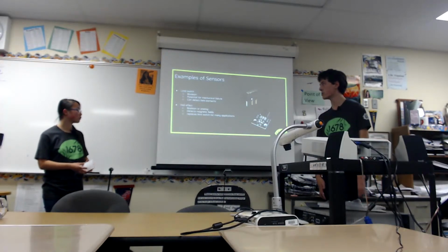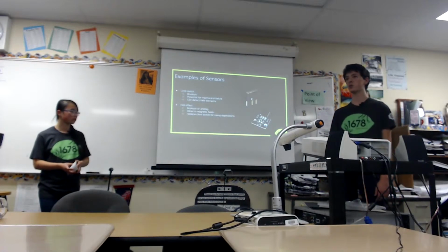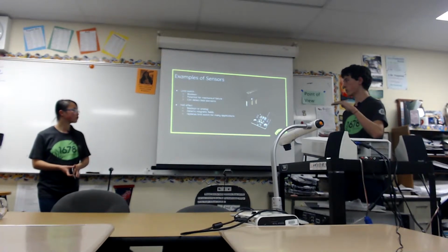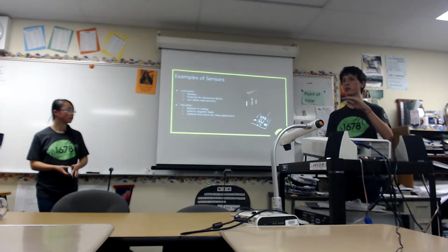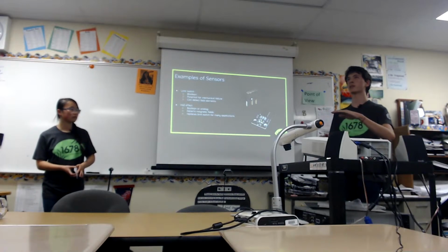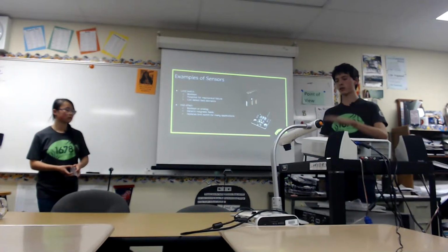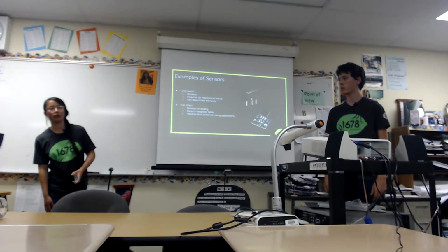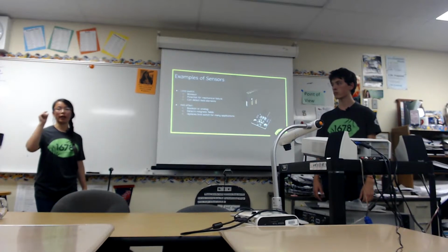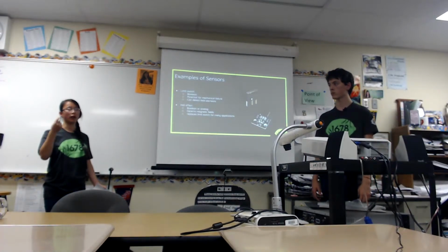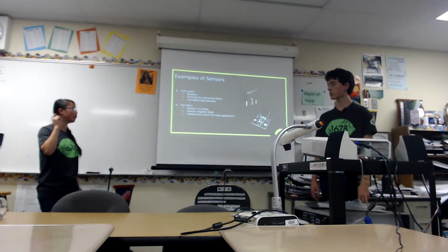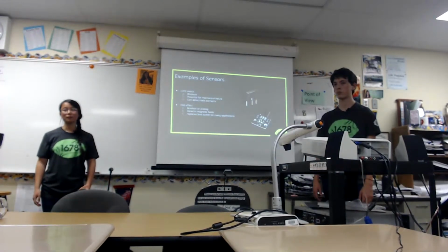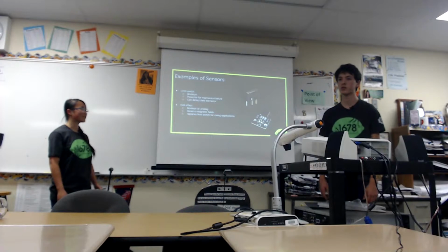Hall effects are similar to limit switches, but they use a magnet and an electromagnetic sensor on the board, and it detects when the magnet enters. The sensor detects when the magnetic field comes close enough. We use this on our elevator for positioning. We had the magnet on the elevator and the sensor at a certain height, so you know when it reaches that height. So is that just for your limits, or was that for your zeroing also? That can also be used for zeroing, yeah.